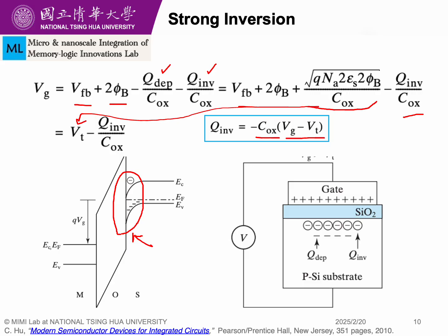So now, this is typically a p-type substrate, and we will not have enough electrons to go for the strong inversion. So what happens? That's why I told you the MOS capacitor is fundamental, but it is not something that is widely used. So what we do, we just add two highly doped regions here, as we showed in the beginning, and those are the N plus regions, and they act as the supplier of the rest of the electrons, which we will learn very soon.